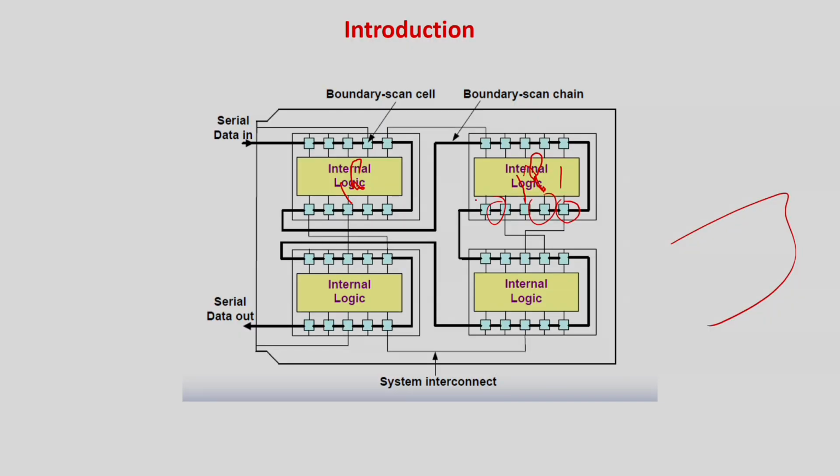So the problem will really happen if I have to apply a lot of test patterns at this pin to test it. So in testing of IP cores, or any core in that fashion in case of embedded systems, the main problem arises: how to access these internal pins and how to apply test patterns there. That is the main challenge. And in today's lecture we are going to look at how I can access these internal points and how I can apply test patterns to them.